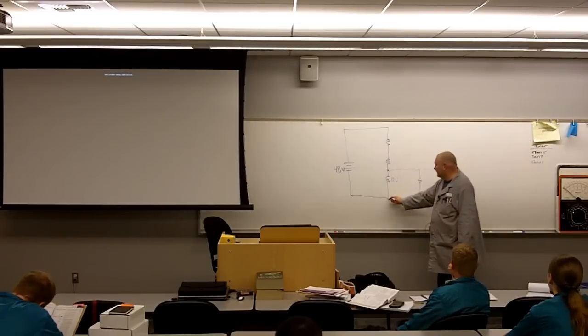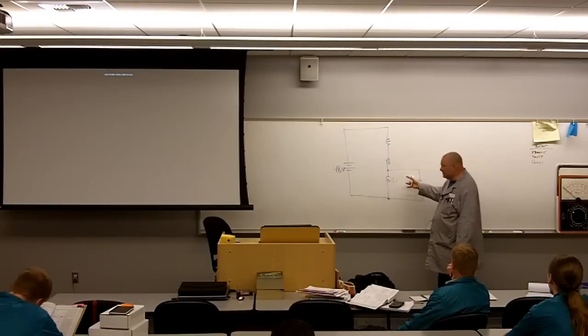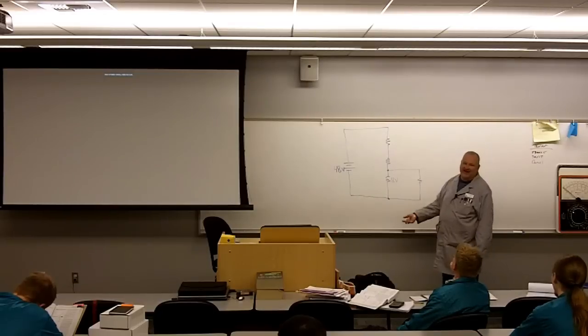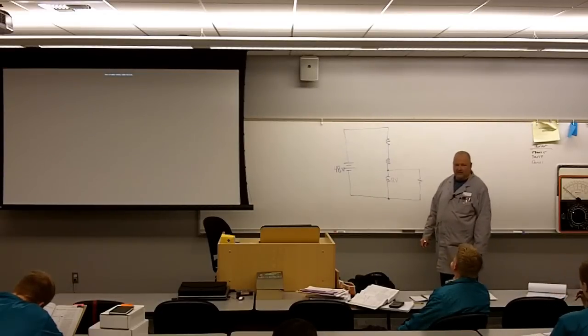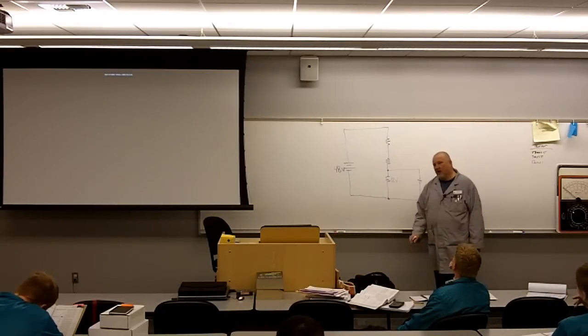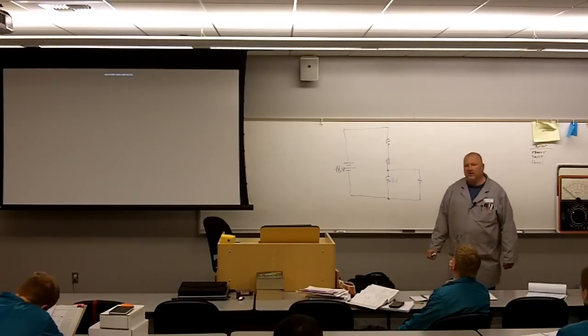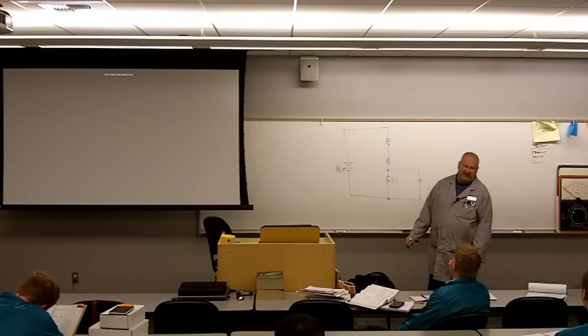Do you agree that that's in parallel? So whatever voltage is here is going to be right here. When I did this, I just changed the dynamics of the circuit. I just loaded the voltage divider. So we're going to call this a loaded voltage divider now.